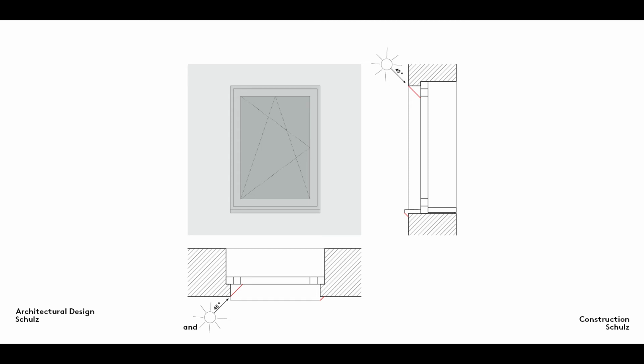Then draw lines from the points at which the guidelines intersect with the shadow projection planes to the elevation so that they intersect with one another and with the edge lines of the shadow cast by the projecting elements. Finally, hatch in the areas between the guidelines with clean, thin lines to create a grey effect.